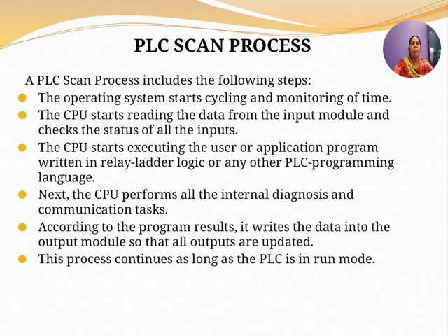Next, the CPU performs all the internal diagnosis and communication tasks. According to the program results, it writes the data into the output module so that all the outputs are updated. This process continues as long as the PLC is in run mode.